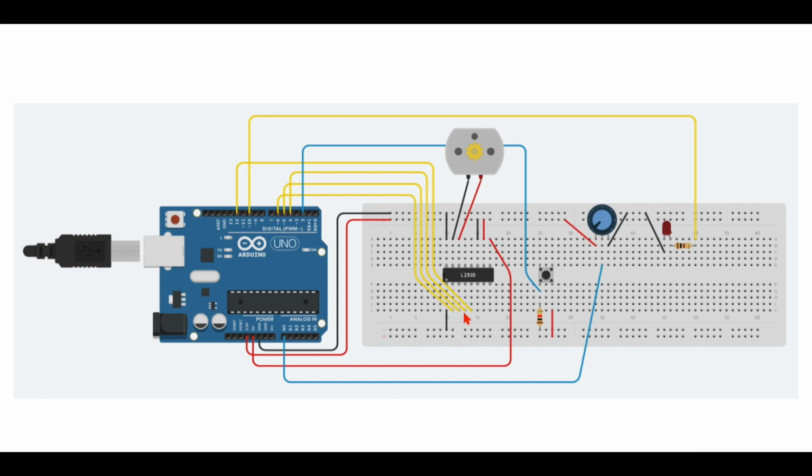And then these next 2 digital outputs are simply just on and off. When one of them is on and the other isn't, it will go in one direction, and when they're reversed, so the other one is on and the other one is off, the motor will spin the other direction, and when they're both on or both off, the motor will be stopped. So in your code, you can set those 3 outputs to what you want to manipulate how the motor will go.